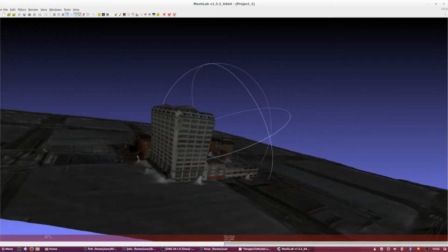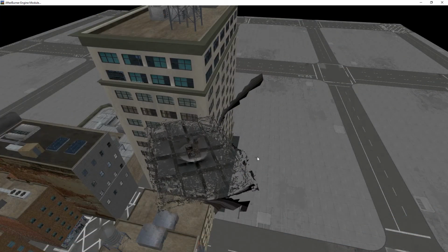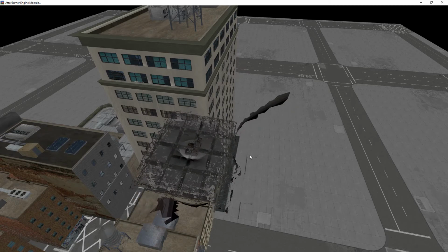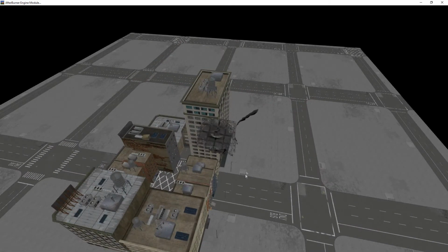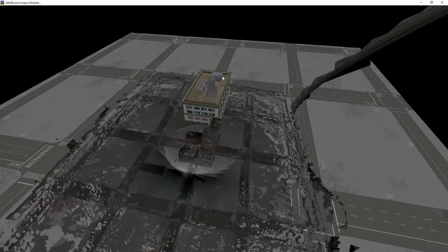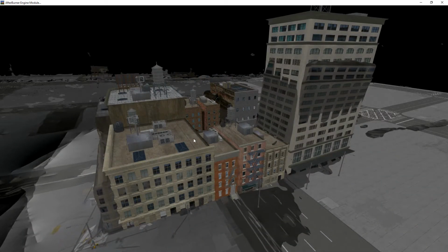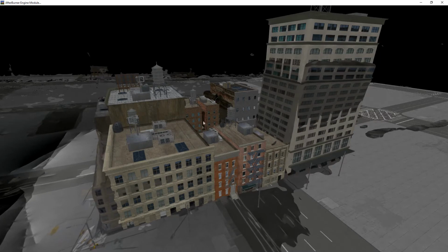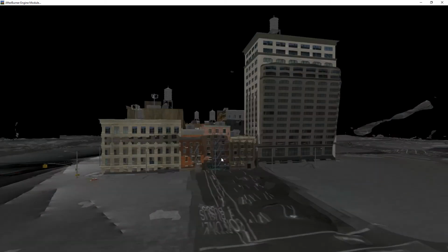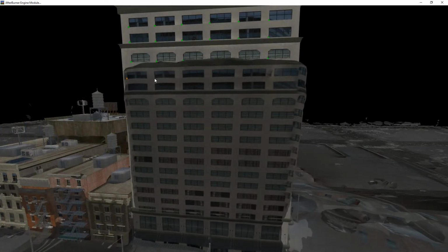When the structure from motion process completes, a three-dimensional reconstruction model is produced, which can be imported back into the virtual world with the true scene for comparison. Before comparison can take place, however, the reconstruction must be aligned by scaling, rotating, and positioning the reconstruction. Care was taken to ensure the reconstructed road was level with the original, and the bases of the building walls of the original and the reconstruction were similarly lined up. With initial alignment complete, it is obvious that the structure from motion process has shortened the height of the original scene. To quantify this shortening, a set of geopoints is chosen for reference and error measurement.